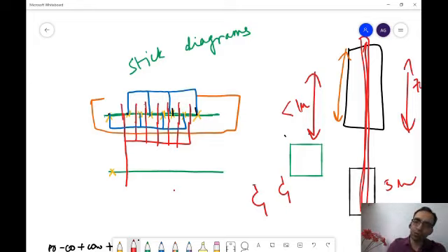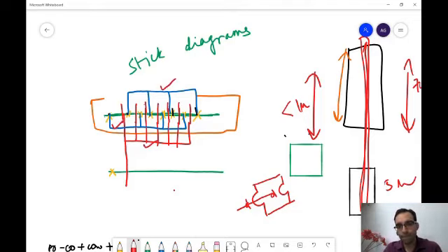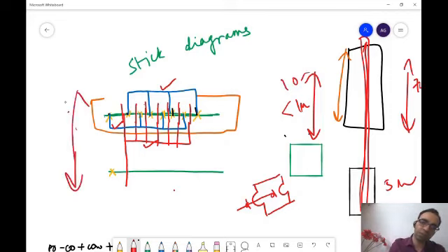So what do I need to do to make 2 devices in parallel? I need to short their gates and the sources and the drains. There are 3 nodes that I need to short. Am I right? Yes, sir. That is what I'm doing: 1, 2, and 3. So now, whatever device size, whether you want to make 7 microns or 10 microns or whatever, can you make it within a total height of, let us say, 1.5 microns or something? Can you make it? Yes, sir.